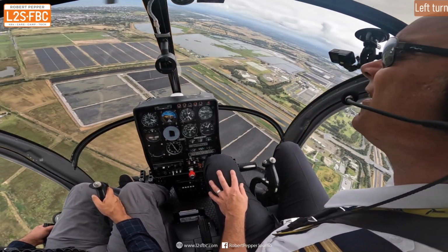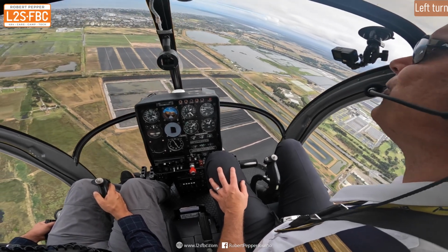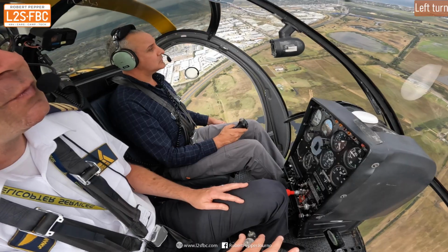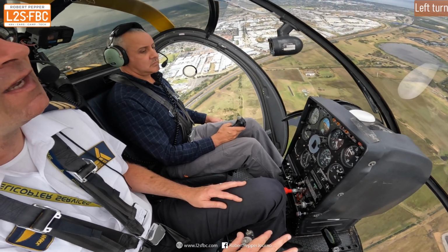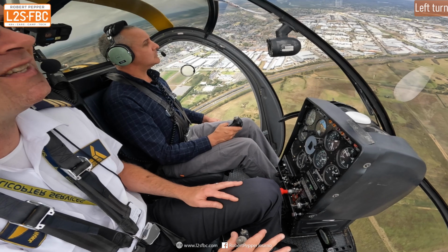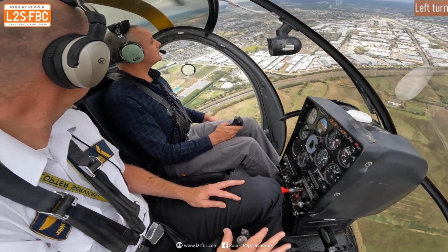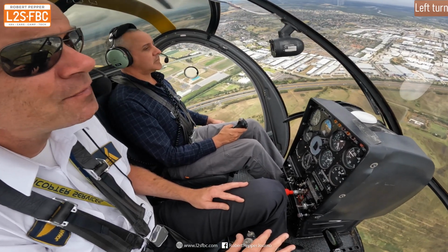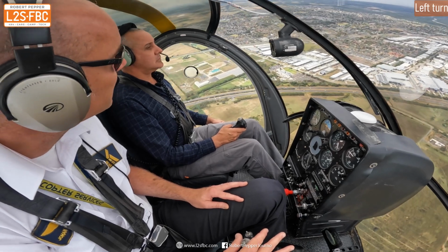Now because the aircraft is banked, we then need more lift, which means more drag, we need more throttle. Now in a fixed wing aircraft that's pretty easy, just increase the throttle, but of course in a helicopter it's more complicated. You've got to bring the collective up just a little bit, and that's got all sorts of further effects you've got to deal with. That's just the joys of flying a helicopter.